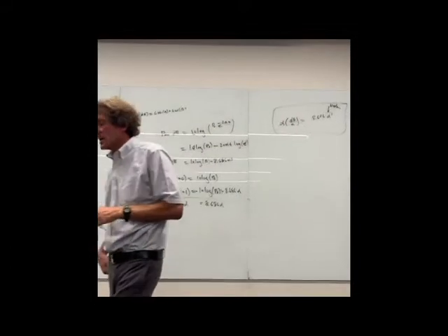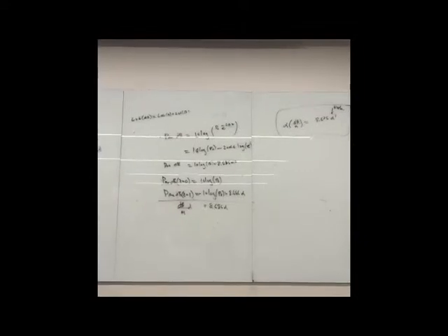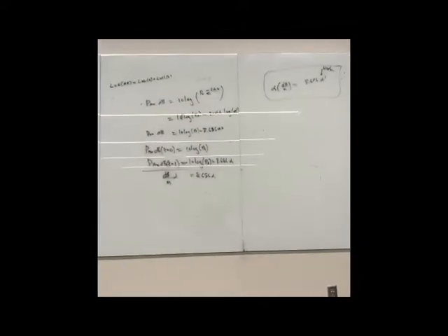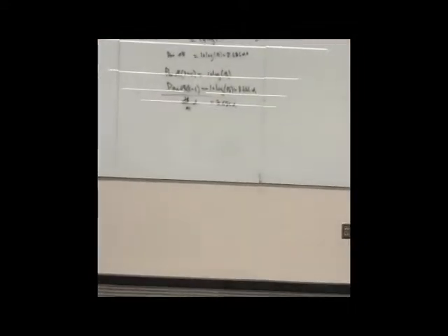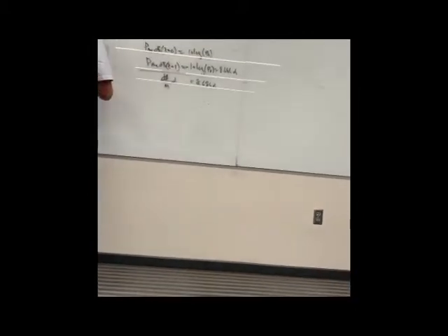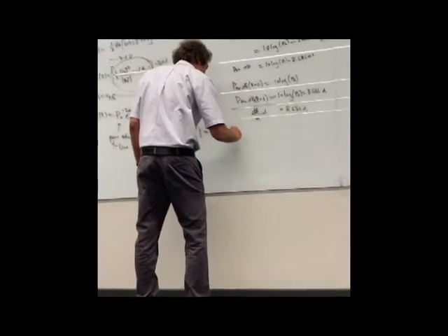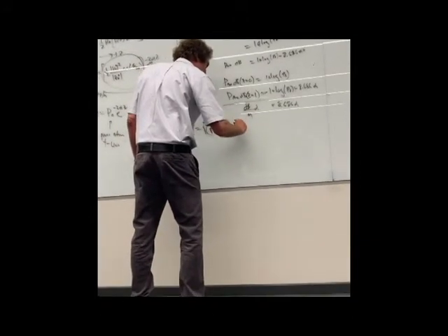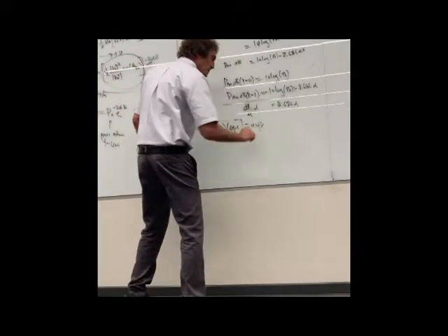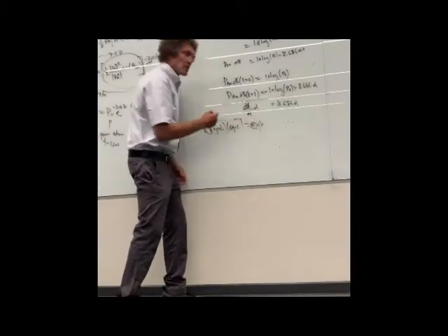Because you might calculate alpha from one set of equations. When we calculate alpha using the propagation constant, gamma is the square root of (R plus j omega L) times (G plus j omega C), and we end up getting alpha plus j beta, right? That alpha is in Nepers per meter. Got me on that one?